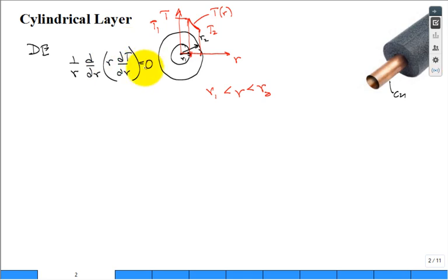It's second order. Hence, we need two boundary conditions. So boundary conditions are T at r1 is equal to T1, and T at r2 is equal to T2. It's both specified temperature boundary conditions. All right. What's the strategy? Good differential equation, two boundary conditions. You separate and integrate, then you do it again, separate, integrate. You have two constants of integration.